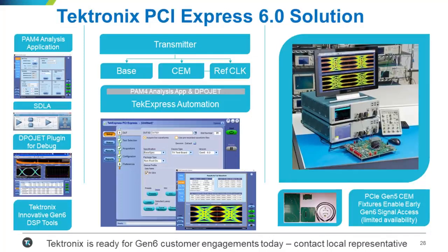I think that one's pretty well understood. The spec's not officially released, so it could change. But I think 50 gigahertz is what we're looking at, and then we're utilizing that BT filter, the fourth order filter, with a bandwidth of 33 gigahertz for 3 dB to do some additional removal of noise.